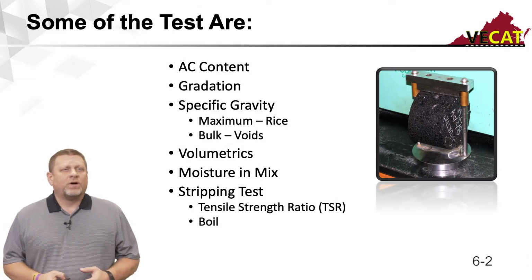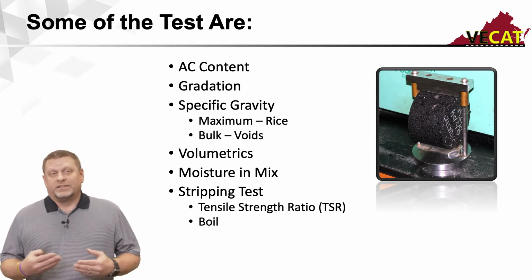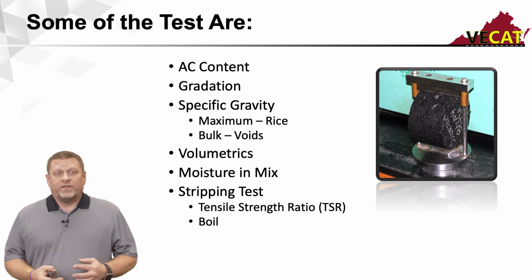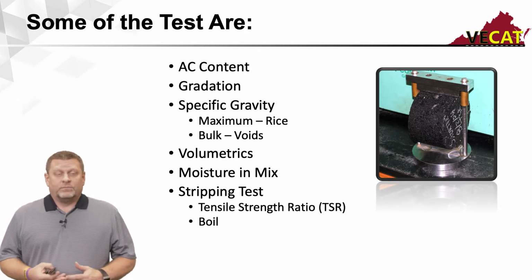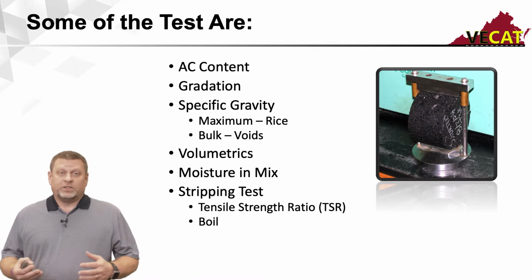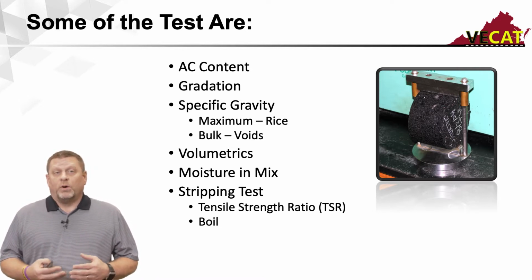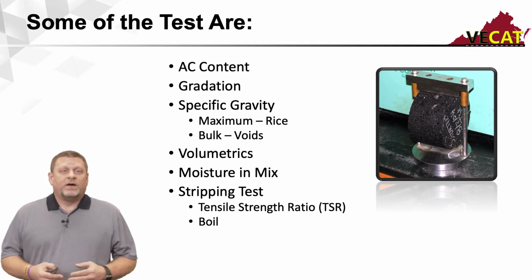Some of the tests we run are the asphalt content, which is measured through a furnace burn, and a gradation analysis, which will be the focus of this presentation. In additional presentations, you're going to hear about specific gravities, both the theoretical maximum specific gravity, or RICE. The reason it's called the RICE test is because a gentleman with the last name Rice invented it, by the way. Also, there's a bulk specific gravity test, where we measure the voids